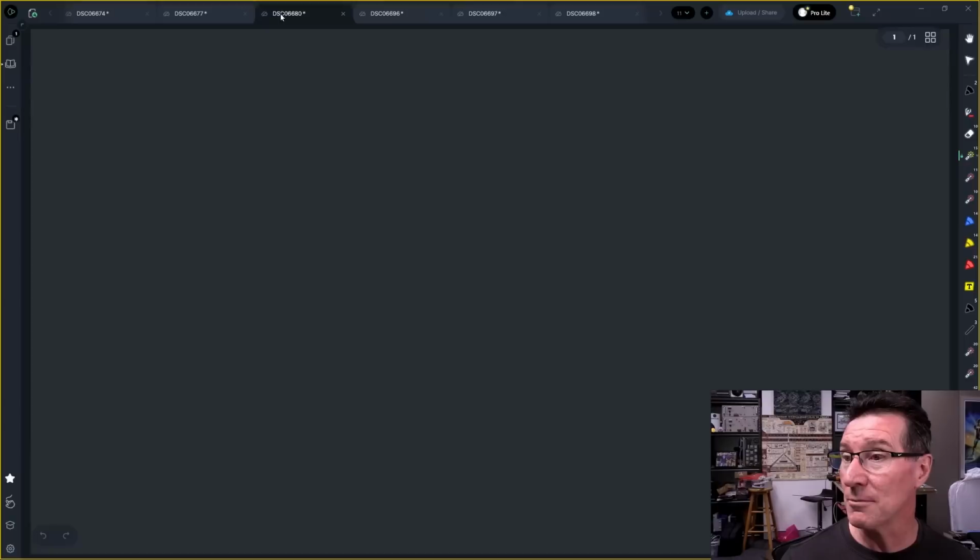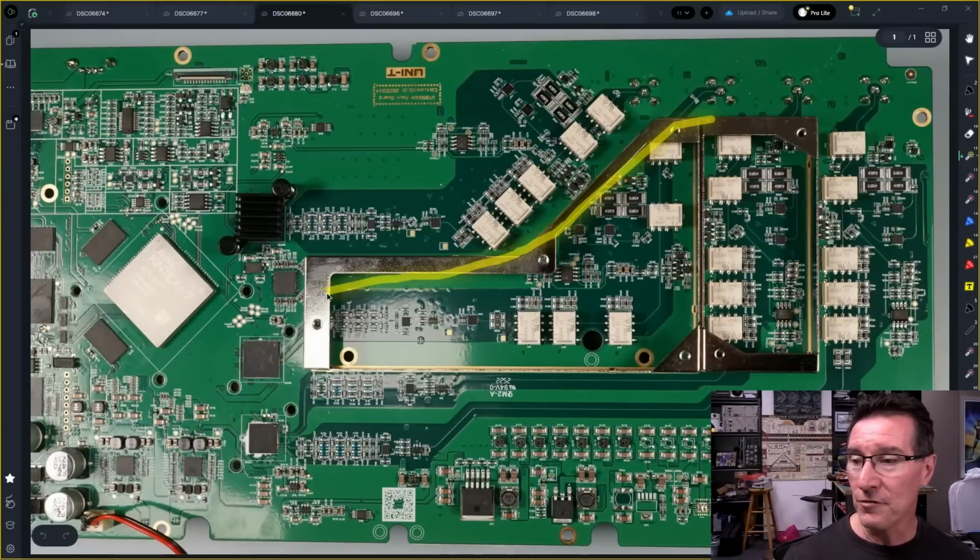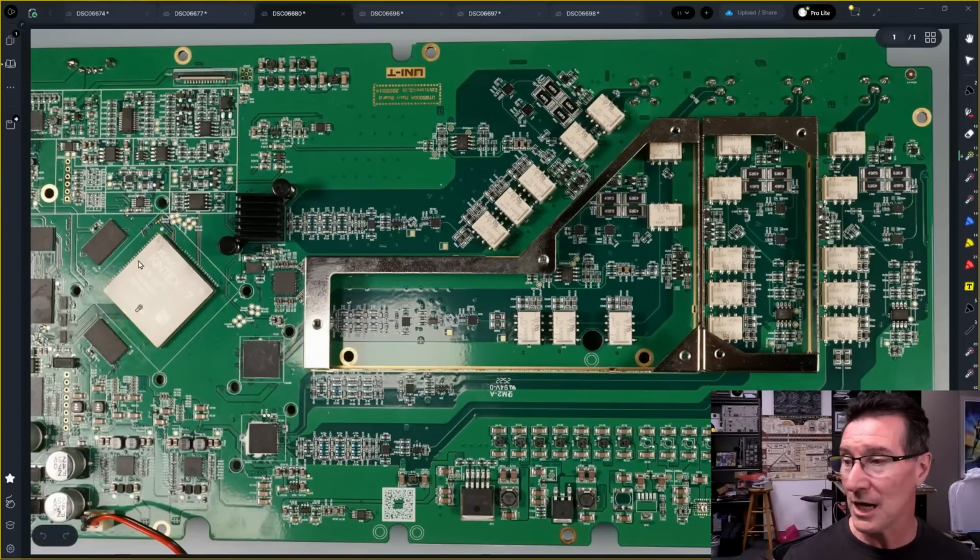Now, let's go over to the main board over here, and I've removed the metal shielding around here, and there's our FPGA, which we'll take a look at. It's a Kintex 7 here. Main processor over here. We've got our waveform memory. We've got our DACs here, and here I only took off these two heat sinks because these will be identical parts, and you can guarantee that.